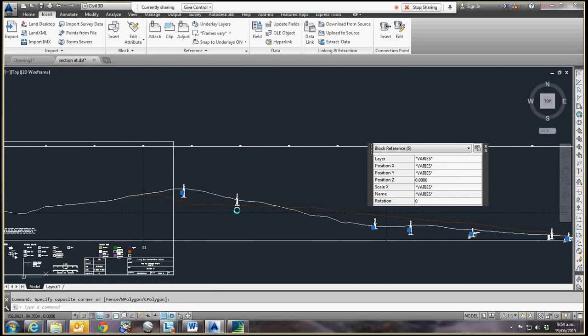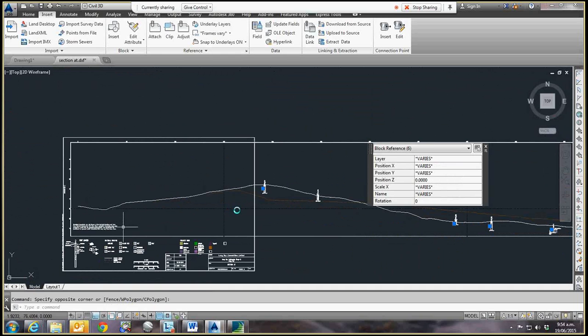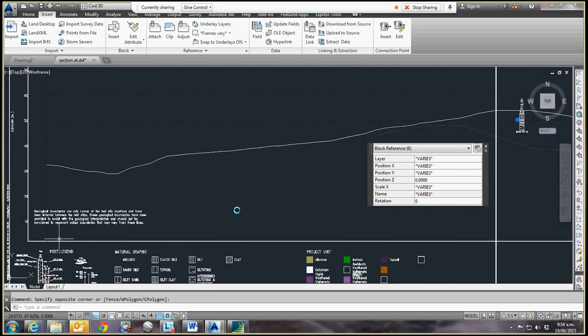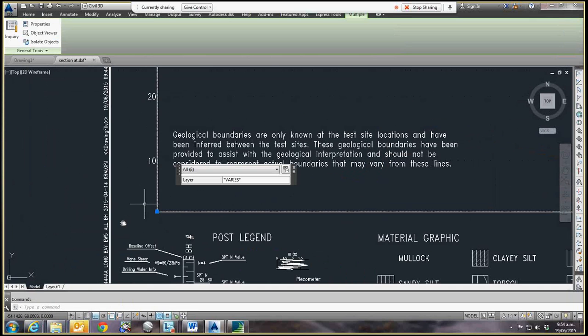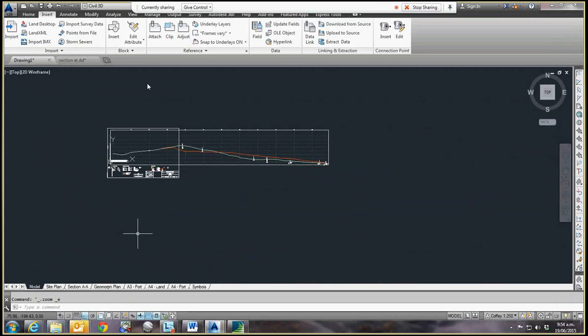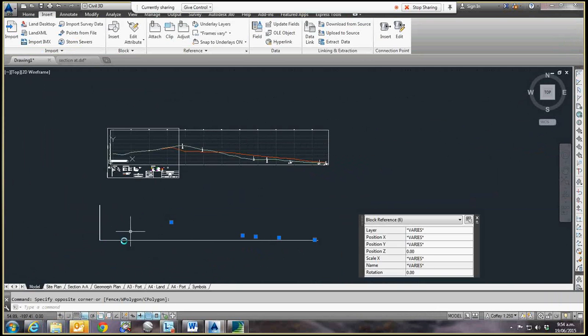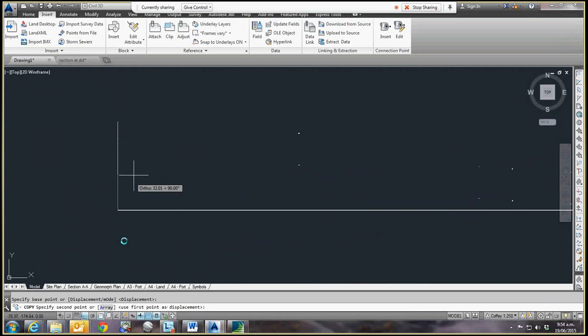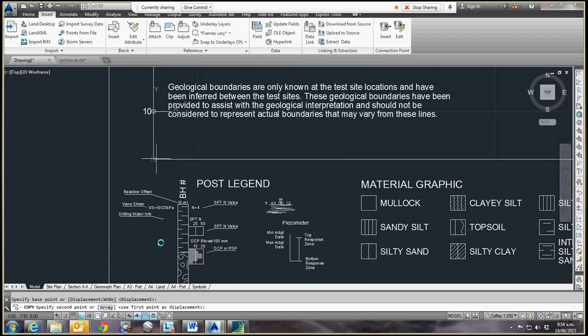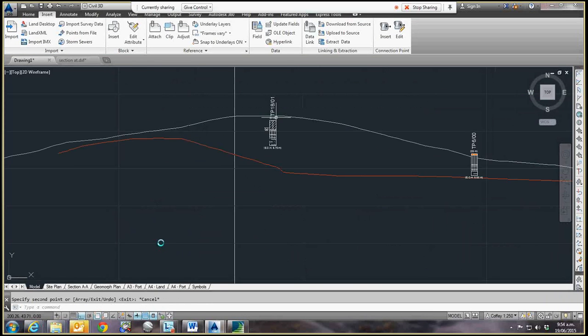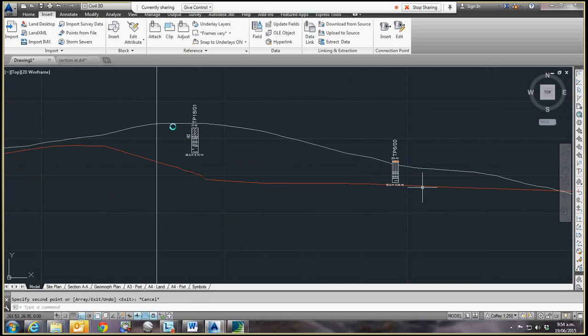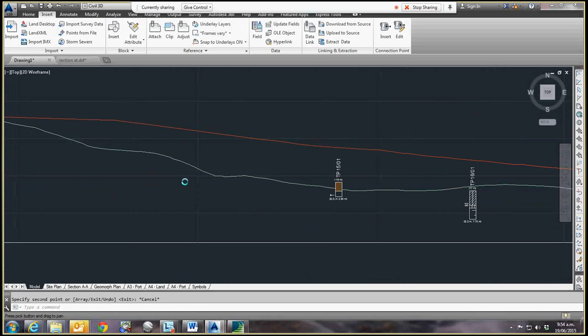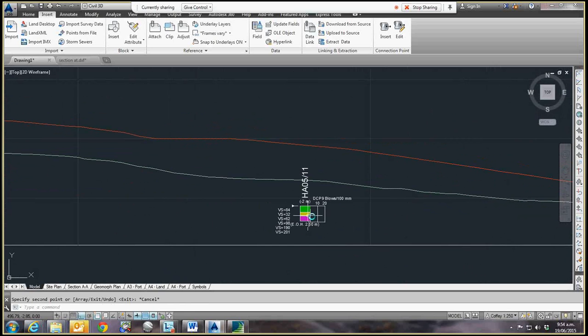And then I usually click a base point too that I can recognize, such as the corners, and I'll copy that into this drawing. And then I can highlight my watermarks and copy from that exact corner. And that corner matches exactly that corner. And now you can see that my watermark landed exactly where it was supposed to, right level, right location. That's the easiest way to fix that problem.